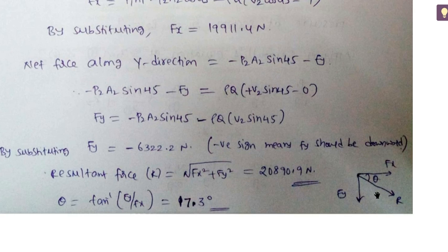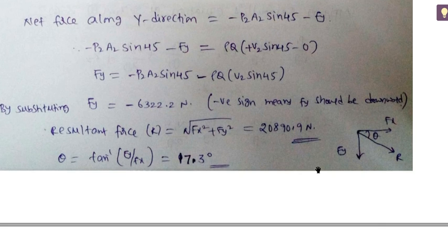The direction we have to find by using tan theta equals Fy by Fx. From that, theta equals tan inverse Fy by Fx. Here theta is the angle made by the resultant with the Fx.